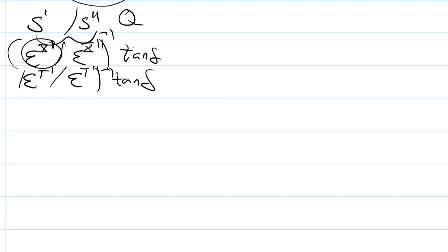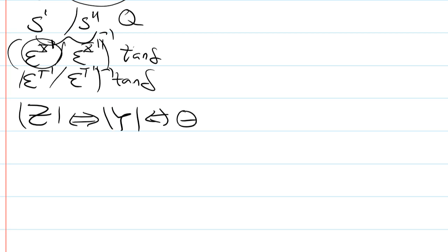The other thing in Comsol, it doesn't calculate impedance or admittance for you right off the bat, or phase. You have to put those equations in. I have a couple of videos on Comsol for this. If you look up Comsol Learn Piezo or Comsol FEA piezoelectric, it'll be one of the first videos on YouTube.